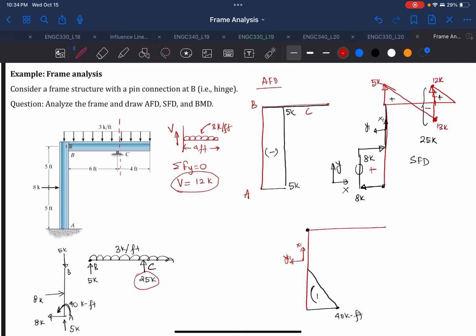And so if it is positive around here, around C, it'll go, and how far it'll go, it reaches the maximum at where the distance is a, where the shear force is equal to 0. Here the shear force is equal to 0. That will be where you find the maximum moment.